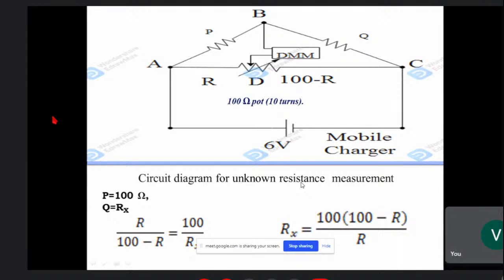The only thing is, in the main circuit, you will have to get a very small current from a small source, in the microampere range, and the source EMF should be very small also. Or you can add a mega ohm resistance in that circuit. Yes, that you will try later on, because you will have to measure microvolt range EMFs.